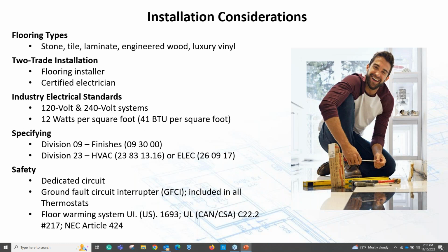A lot of people want to know about the 120 versus the 240 system. Does the 240 system heat the floor up any hotter or quicker? No, it does not. Basically, the 240 system just allows you to cover more square footage. So a good little mnemonic device to remember is that most manufacturers, if not all, at 120 volt, normally cover about 120 square feet of heated space.